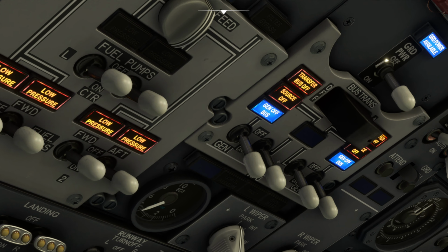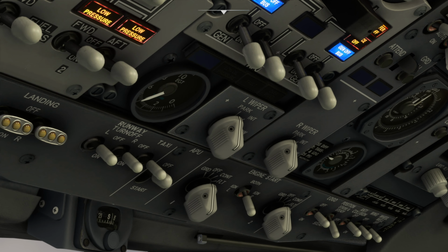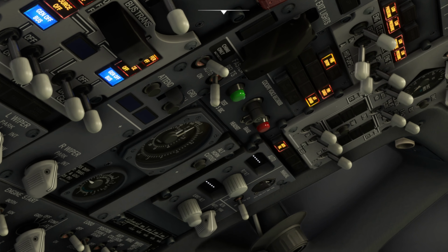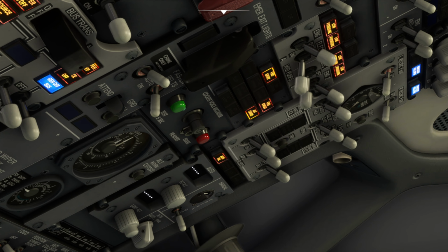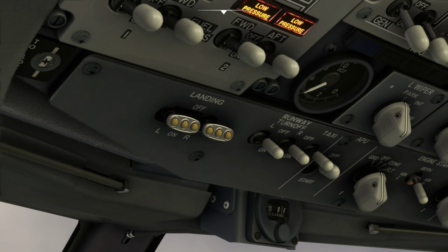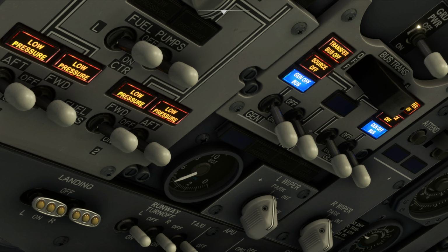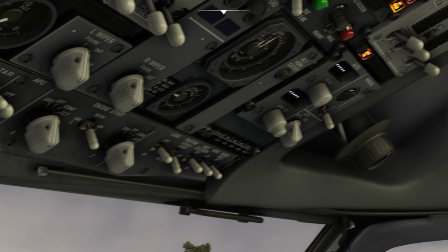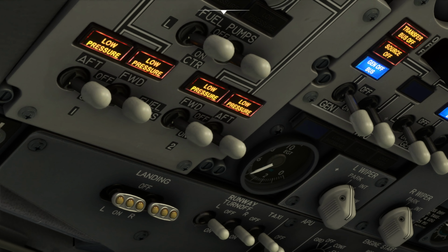Once the APU shuts down, which again will be evidenced by the drop in exhaust gas temperature on this gauge, we will have no ability to generate hydraulic pressure or pneumatics, or really any usable degree of electrical power beyond just being able to start the APU. Again, expecting a caution and warning just to tell us that we are discharging on the DC bus.